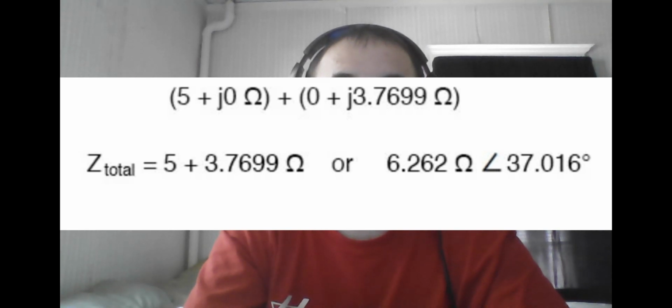So we can also get a form of Ohm's law that works for complex AC circuits by stating voltage equals current times impedance, although it should be somewhat obvious that voltage and current would be complex vectors as well. They would not be simple numbers like in DC circuits.